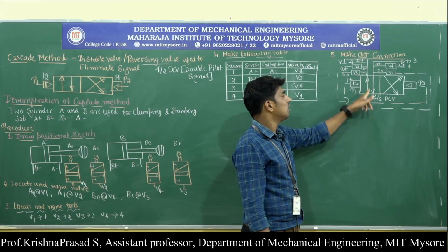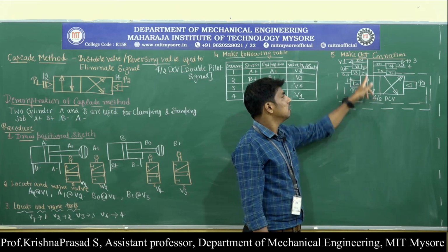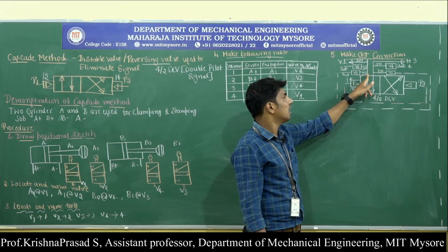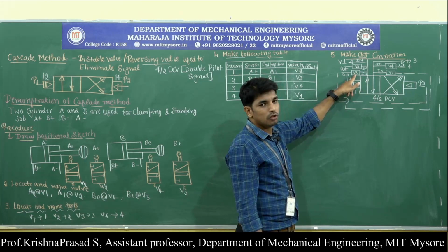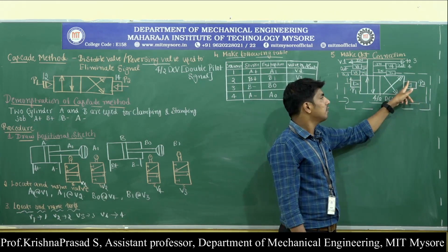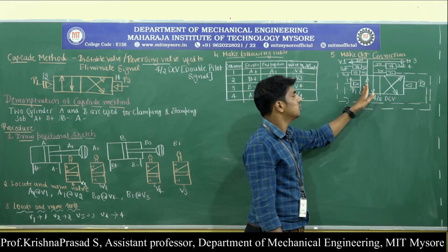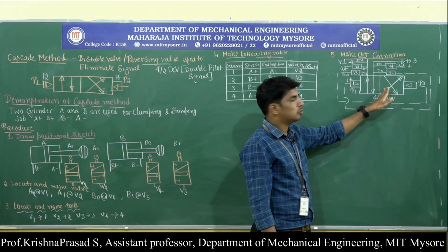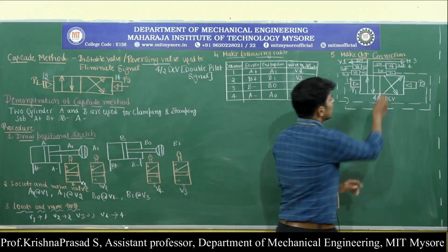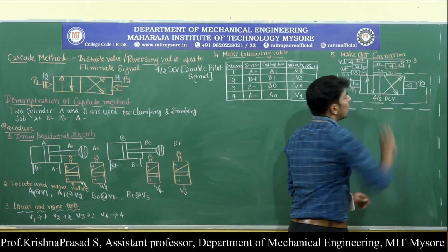But what about V3? When the pilot signal is activated, the highly pressurized air from the input goes to pilot signal P2. Once pilot signal P2 is activated, the normally open position is shifted to the normally closed position. Then the pressurized air goes to V3.